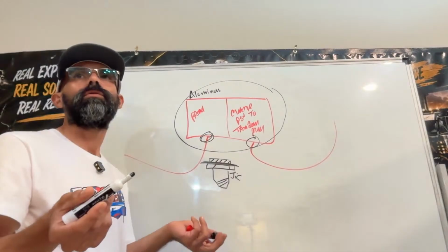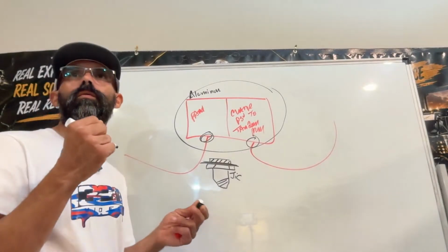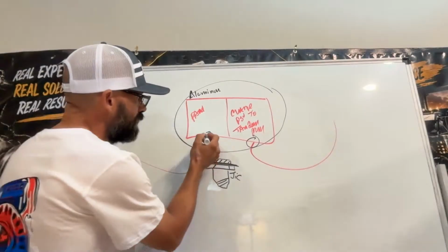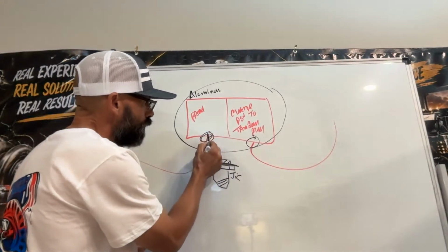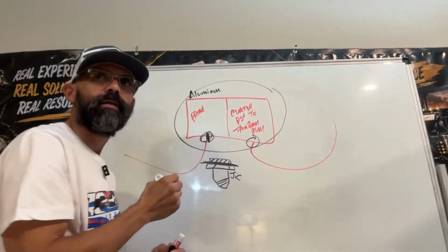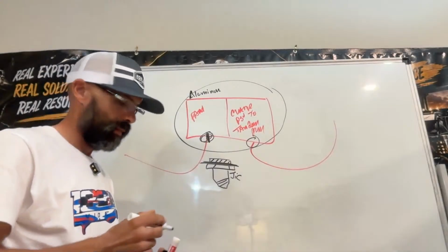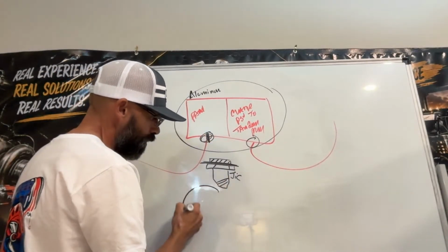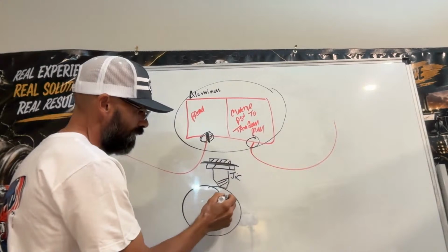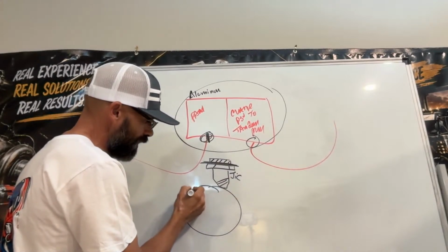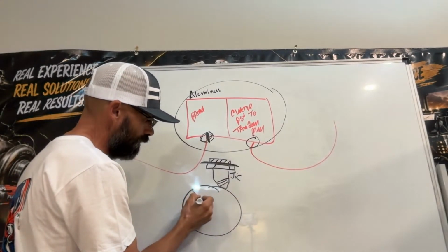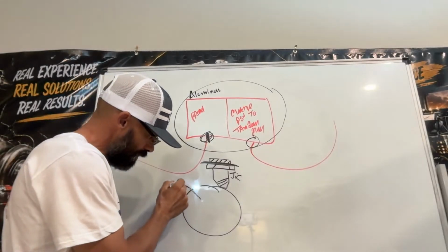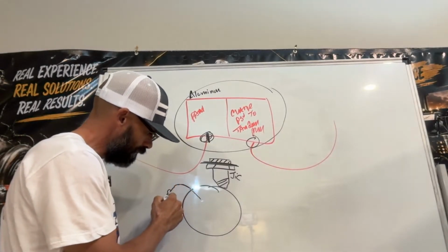All you gotta do, if it is leaking, inspect the O-ring. Well, the O-ring doesn't look too bad. Oh, okay, you know what? I gotta pull the pump. You gotta pull it out, unfortunately, because you gotta see the hole where the fitting goes, if the threads are cracked. Let's say this is the hole where the fitting goes. You're gonna see a hairline crack that goes all up into the housing. And that's why your pump keeps leaking.